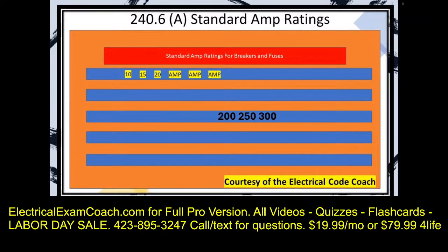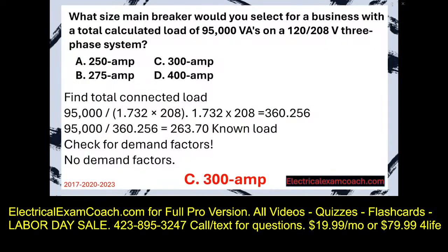And this is where the beauty happens. We're going to now put this on a 300 amp breaker instead of, like in the previous question, a 400 amp, meaning that we'd have to have larger wire in the previous question, which may lead us to have larger pipe, which we may end up with a larger cost of overall project. The beauty of three-phase is the numbers come down. So this one's on a 300 amp service, which means we can put it in smaller pipe, which might end up having a smaller overall cost.